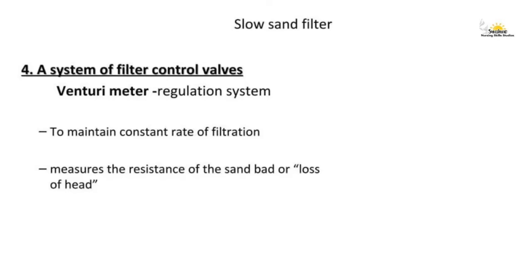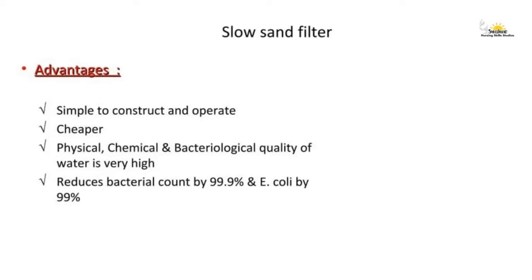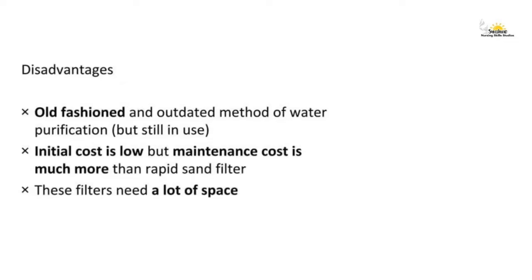And now let us know how to clean the filter. It is done whenever the resistance is high. It is done by draining the supernatant water and scraping the top portion of the sand bed. And now let us see the advantages. It is very simple, cheaper, the physical, chemical and bacteriological quality of water is very high, and it reduces the bacterial count by 99.9%. Disadvantages: it is very old fashioned, the initial cost is low, but later the maintenance will be very high. These filters need a lot of space.